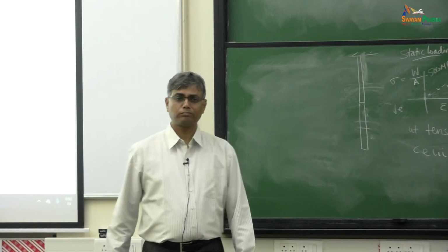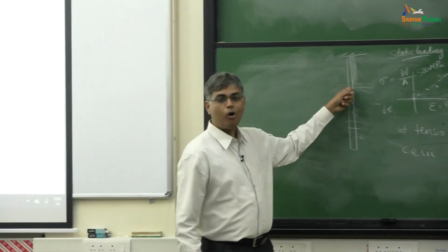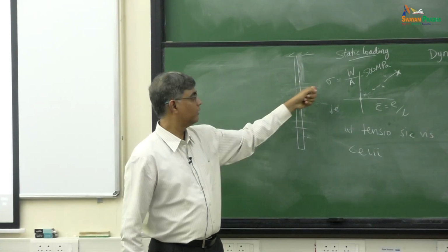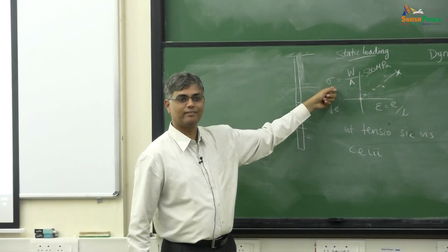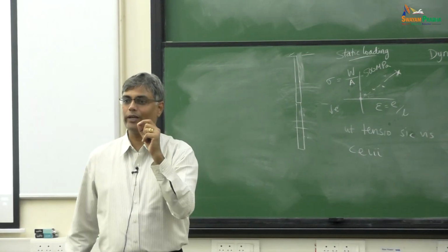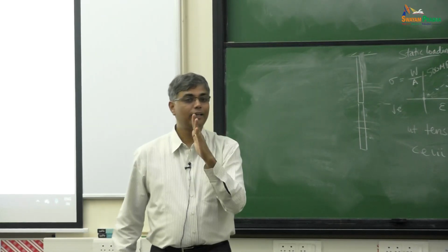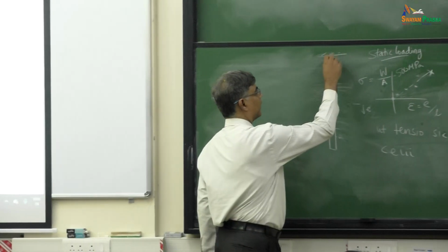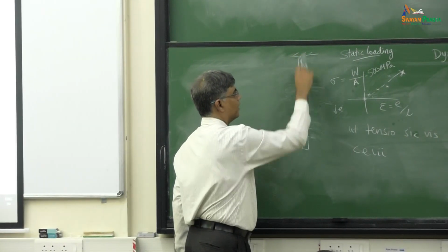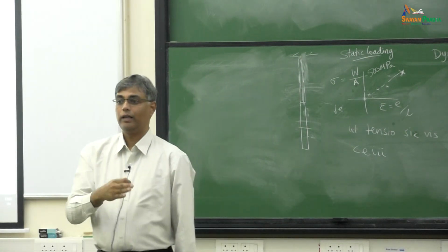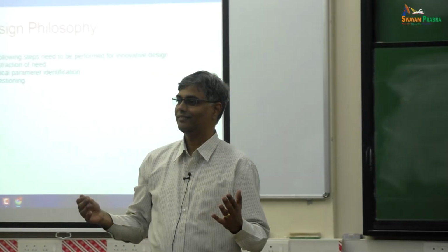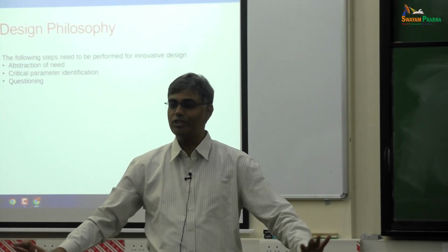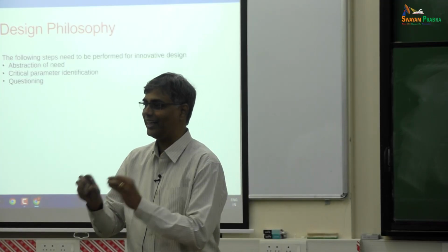If you look at it, it is because of this small leap of faith that we made, going from this wire to this concept of stress. What did we do when we said force per unit area? In our minds, there was a uniform distribution of material, a continuous set of fibers. It is called the continuum hypothesis. So currently, we model all these materials as continuous bodies, where material is there at every point.